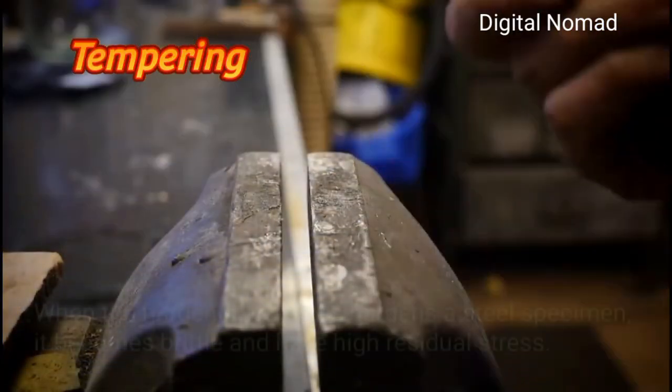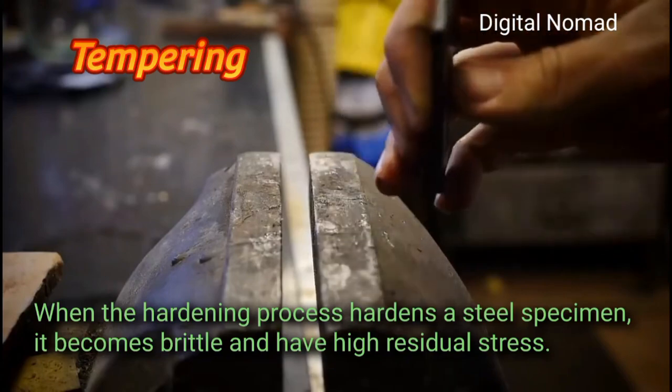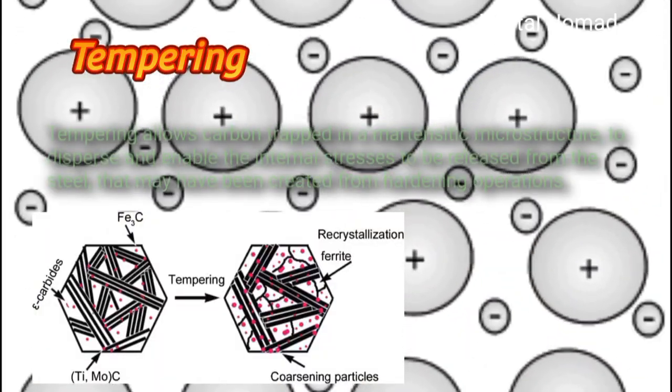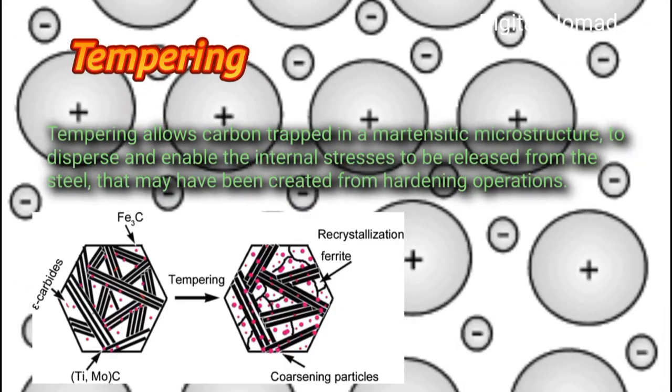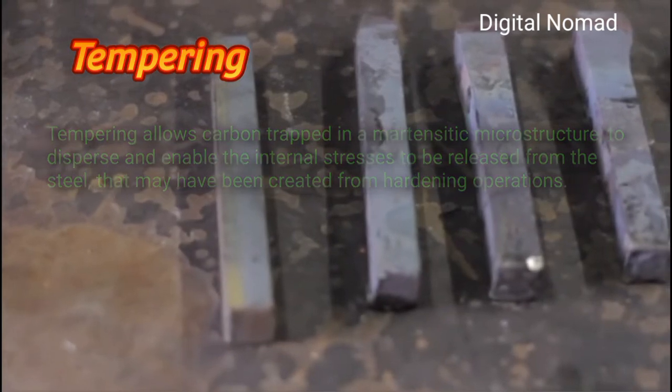Tempering. When the hardening process hardens a steel specimen, it becomes brittle and has high residual stress. Tempering allows carbon trapped in a martensitic microstructure to disperse and enables the internal stresses to be released from the steel that may have been created from hardening operations.